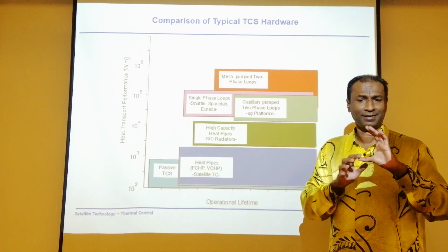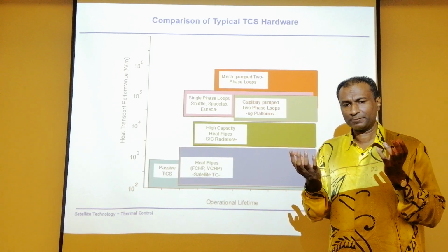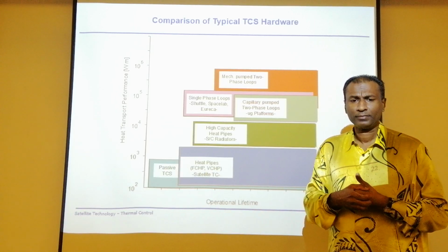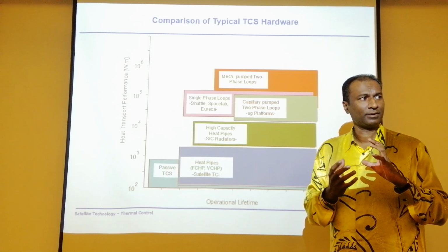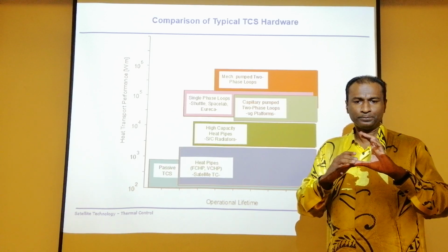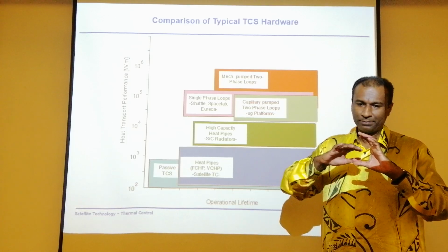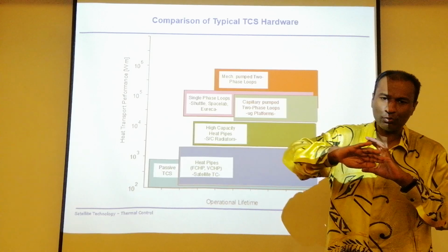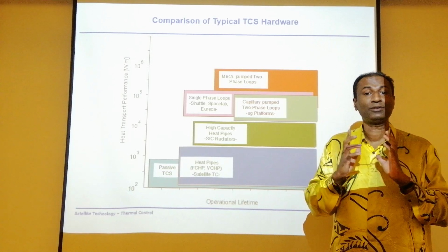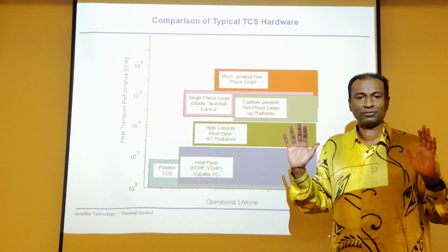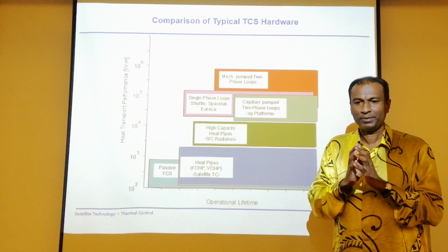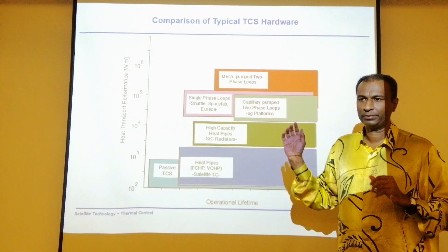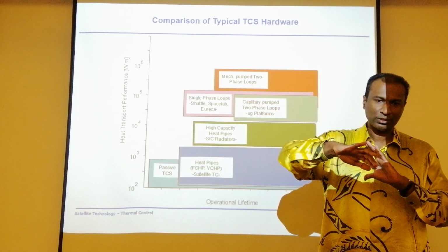What is the capillary effect? When the particular fluid, basically water, maybe ammonia, is heated up, it will evaporate, and the evaporation happens towards the wall, and then the flow is created. That's how. But you need to have the heat. Without the heat, nothing. There's no change of phase. Basically, liquid will stay liquid. So the evaporation will take place in a place called the evaporator that we will see later. Then it goes on to flow.